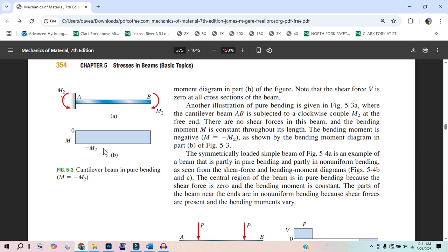You know what I mean? That's what we qualify the y-axis. So in here, it would have been way better just to throw in M parentheses x, so you can see that this line is a function of the x direction. I vary x, take an x value right here, come down and read out the moment. Now sure, any value of x is going to give the same moment. That's what constant moment is. But that could be useful, they should have done that. Anyway, sometimes that is too much. You freak students out by putting too much notation on it, there is that aspect.